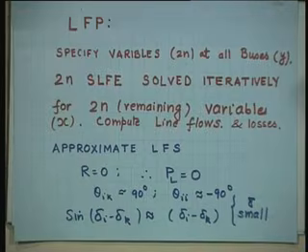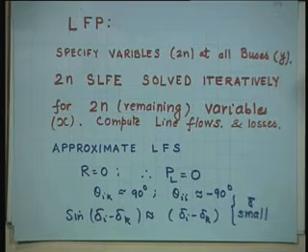Let us now define the load flow problem. Specify 2n variables at all the buses, that will give you the vector y. The 2n SLFE are solved iteratively for the 2n remaining variables x, then compute line flows and losses. That is all we do in load flow.